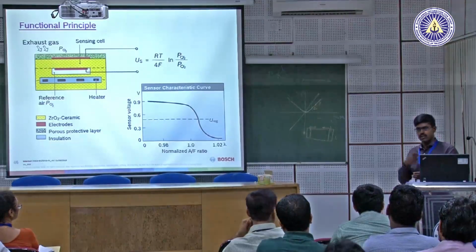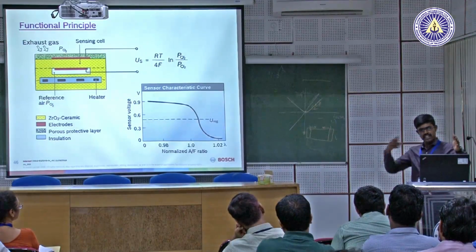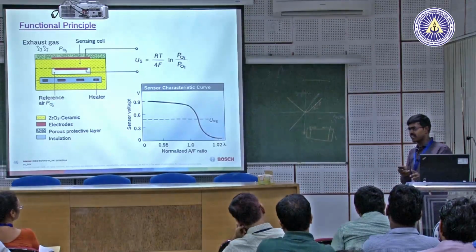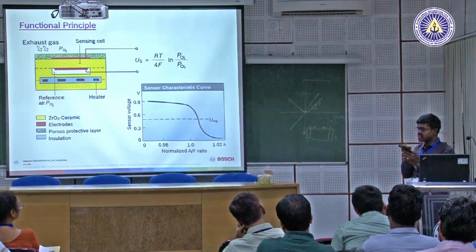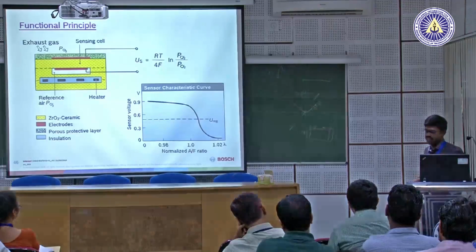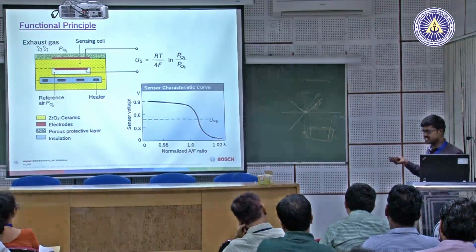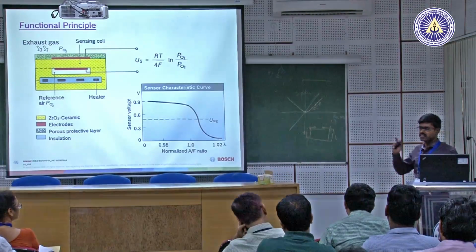It is an improving process. When you change some parameter, it goes rich, you get feedback, you change parameters again, and it may go lean. So it will oscillate like a sine wave around the lambda equal to 1 level. That is how oxygen is sensed here. This switching type just says whether it is rich or lean.